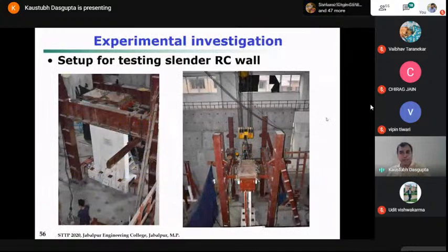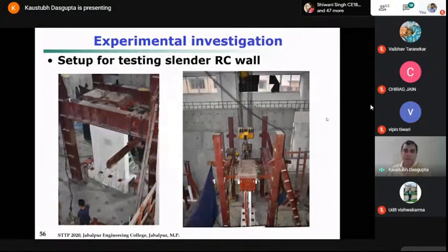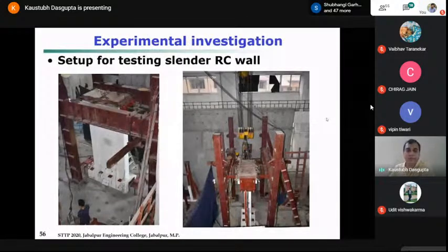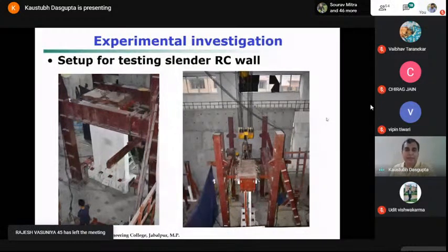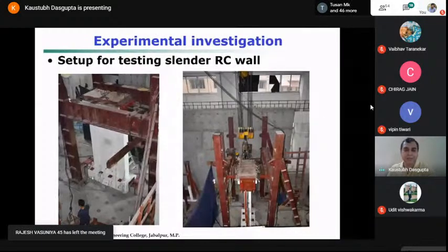So these two figures refer to the portions of the slab attached to the wall directly. That was the numerical simulation by Dr. Snehal Kaushik, and currently one of my students, Soumi Rajbanshi, is trying to see the extent of confinement of the boundary element of the shear wall. In her study, she tested a slender wall in our structural engineering laboratory, and it was a tall wall because we tried to model it as close to a full scale model as possible. It was more than 3 meters in height in total, and you can see this is the base beam, and this was the wall.